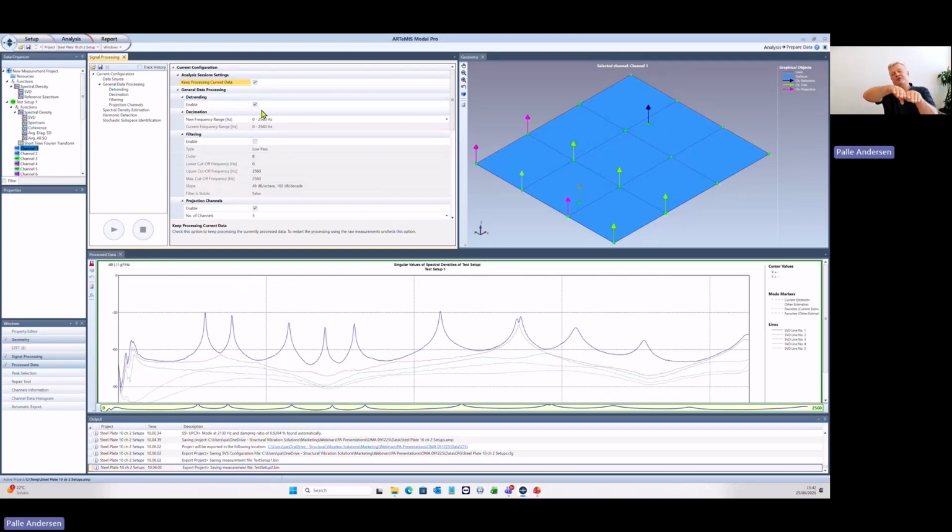Remember that the trend was, if you had a linear trend, a growing or a decreasing kind of trend of the mean value. This one here can actually be removed just by checking this checkbox here. And what happens is we are simply fitting a straight line to the data, and then we are subtracting this straight line from the data. We do that per channel. And in this way here, we then get any linear trend removed so that the trend is now 0. That means that everything is moving up and down around the 0 mean.